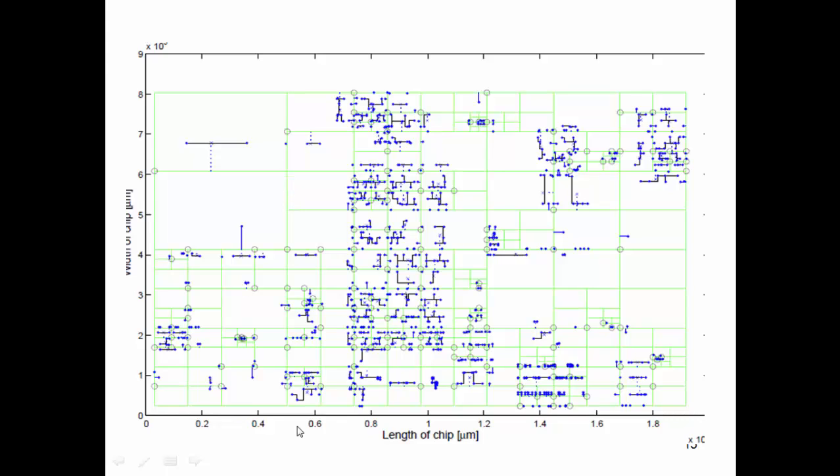So basically this is the capacitance centroid method, where we calculate the capacitance centroid of the sinks and place the mesh node. Supposing for this small room, the capacitance centroid comes here. We just place the buffer at the mesh node closest to the capacitance centroid.